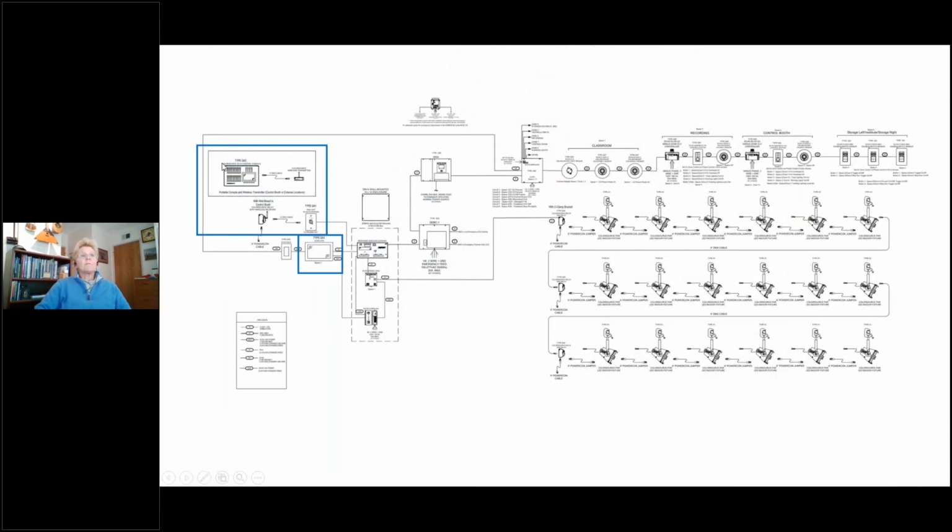That control console is shown here in a riser diagram, and the touch screen in the wall is also shown, and how all of this ties together and all the button stations. Now, all of the house lighting and any other back of house lighting, the storage areas, the vestibule entrance are all controlled off of this panel, and you can see occupancy sensors here and all of the stage lighting here.